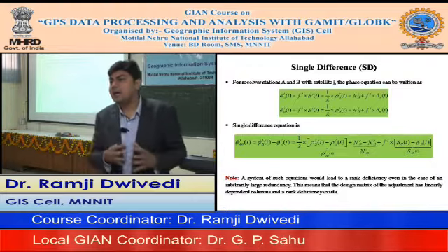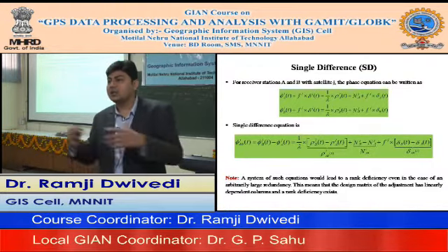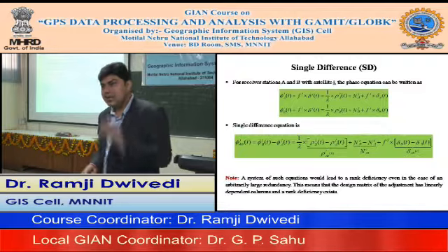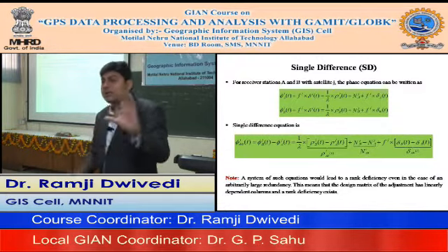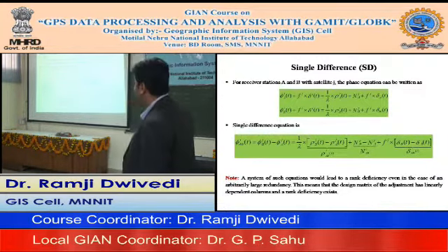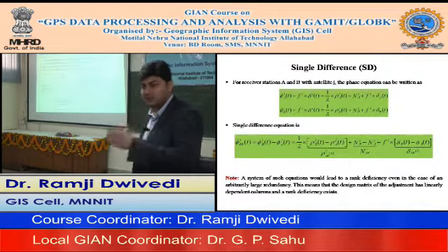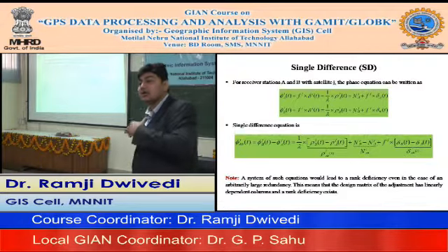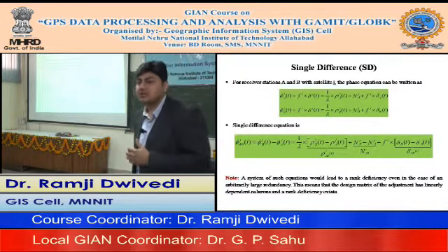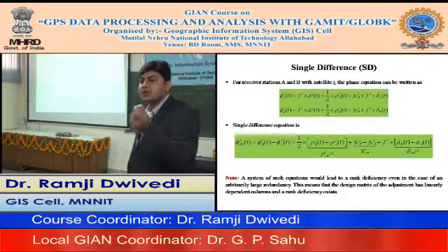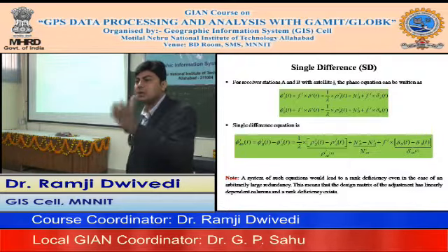So that has to have at least 24 hours of data prior to the observation from your rover, so that it has a fixed coordinate, or you assume that it has a fixed coordinate, so that you could consider it as a base. And generally we use a terminology for those base stations which we have been using for the past 10 to 12 years; we name it CORS, which we call the continuously operating reference station.